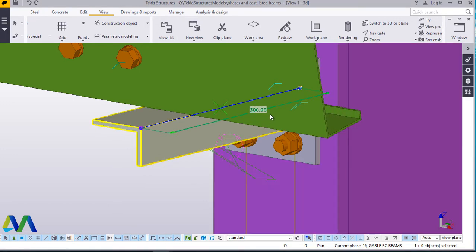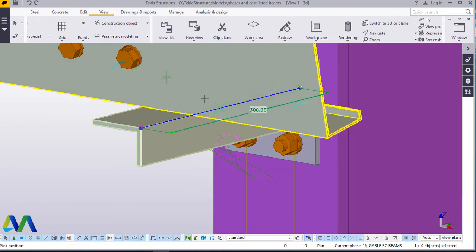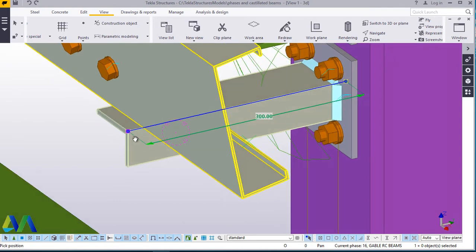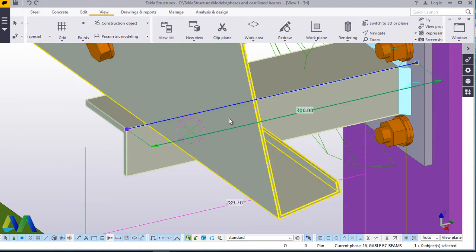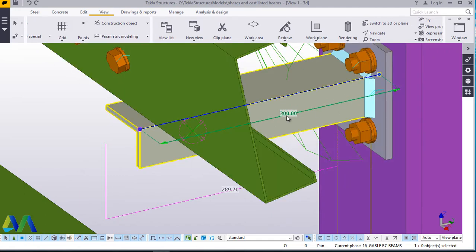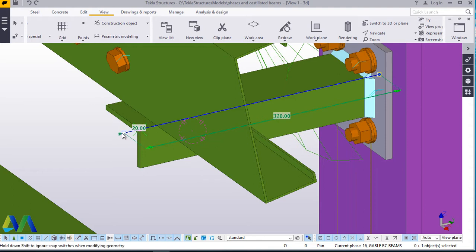Now the next thing is to adjust the length of our support for the gutter. We'll do that by either clicking on this point here and dragging, or we can double click on it and go to DX and DY offsets, but we will use these points. As you can see, the length is 300 and we want to extend this maybe by 200 to make it either 540 or 600, but 540 is okay. Now I'll click on that spot, then I'll be able to drag this.